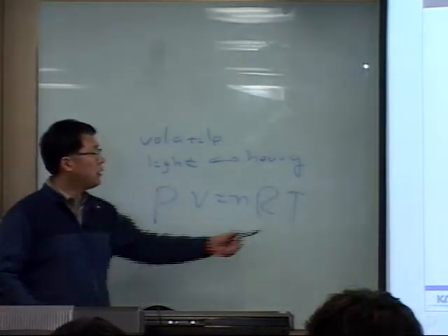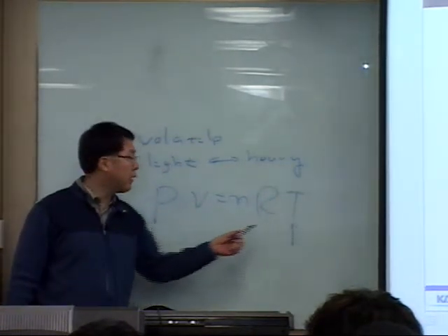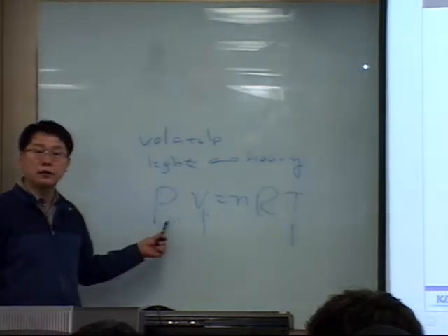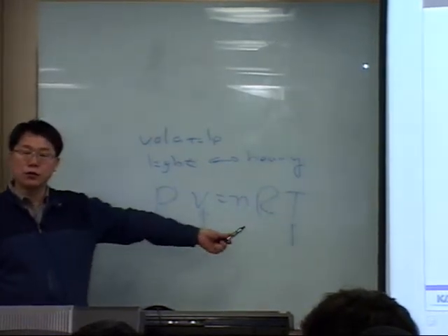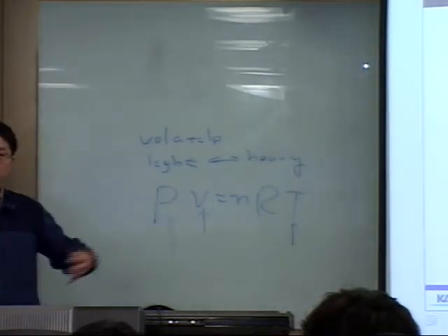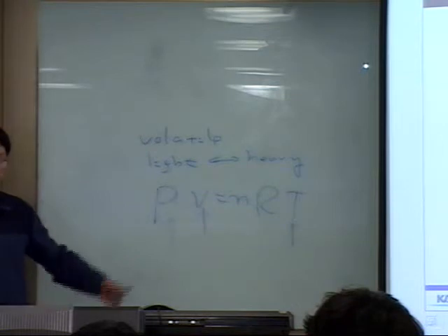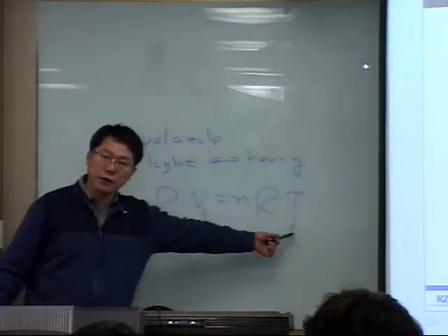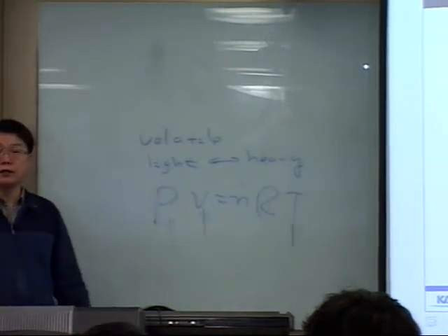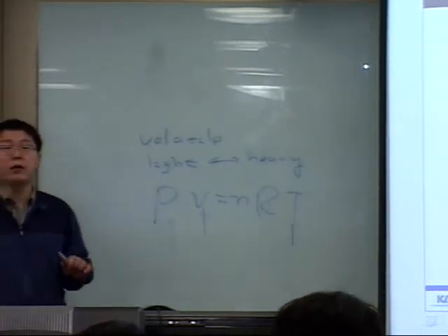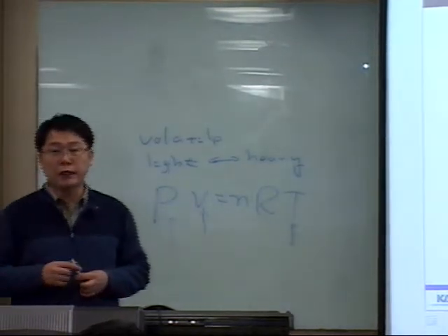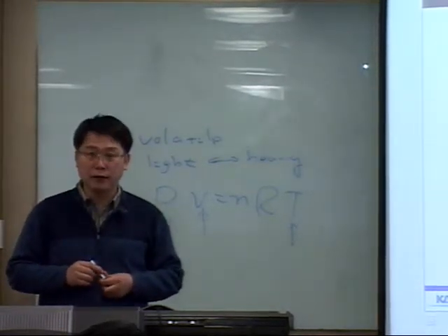The temperature will increase, volume is constant, so pressure will increase linearly with temperature. So if we have a heat ingress from outside, the temperature will increase, and in consequence, the pressure will increase. But we have a multi-component system, and the mixture is in a boiling state.